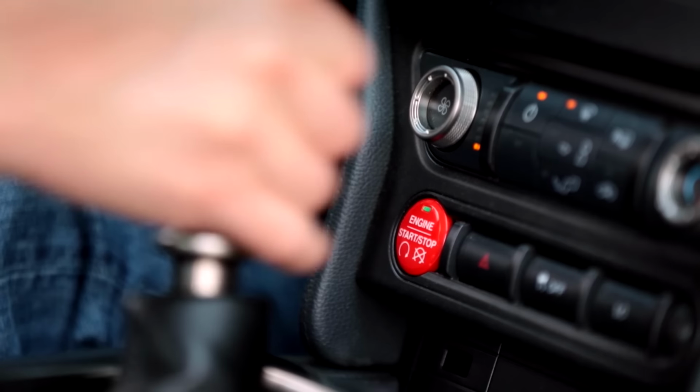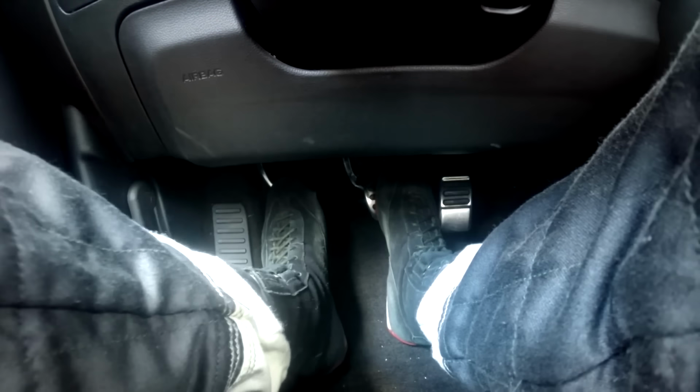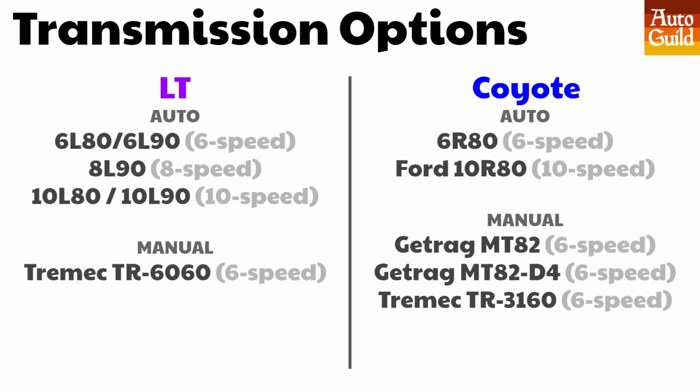Ford has not used the Tremec T56 or TR6060 in any Mustang with the Ford Coyote engine. The Coyote trans bolt pattern, though, is the same as the modular, so in theory, lots of options. For now, the Ford modern automatics don't work that well when installed in old muscle cars, so you need to do your homework because these things may be improving as time goes on.